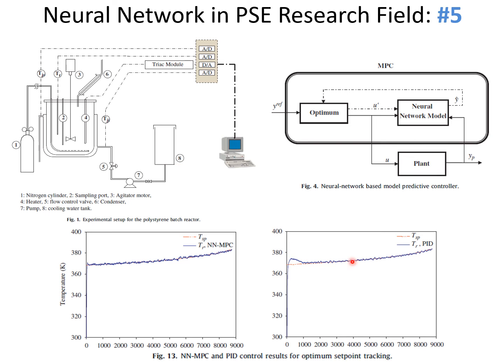Even if you have disturbance, the same thing, it may go out of range. This is again the advantage of advanced control, which gives tight control compared to PID. It may work at the end, but at some point it may overshoot the boundaries, which will make it totally unfeasible, not acceptable. You may have to close down the system and do it again, so it's a lot of time wasted.